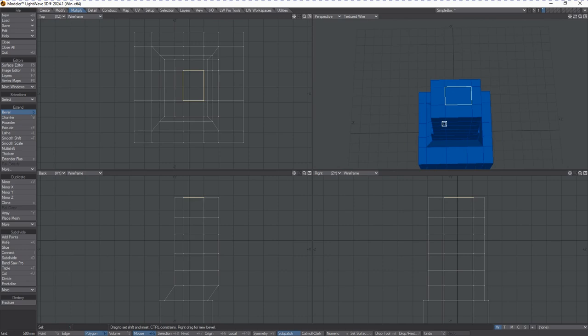Select that polygon. So I'm going to hold this with B, selecting B, and I'm going to hold Control and Shift the polygon by using the left mouse button. And then we're going to inset it by doing the same operation. Again, back to B, and then drag this down so it's like got a little chimney in there. And we can go all the way down to the bottom, giving it some depth.